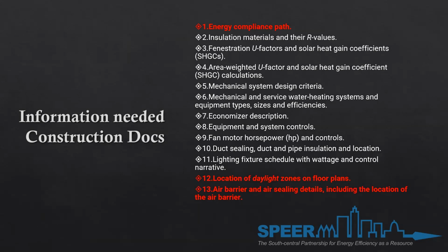That needs to be something specific in your plan review department to say, that's one of the few things you're going to have to verify. And what that's also going to tell is how the inspector in the field is going to look at this project. Because if you do prescriptive, you can easily have a code book in your truck and you're looking at it verbatim out of the book. If it says total UA trade-offs, that book kind of goes out the window. You have some mandatory things, but you can't specifically tell if it's meeting it without looking at the report and seeing the details as to what's been traded off.